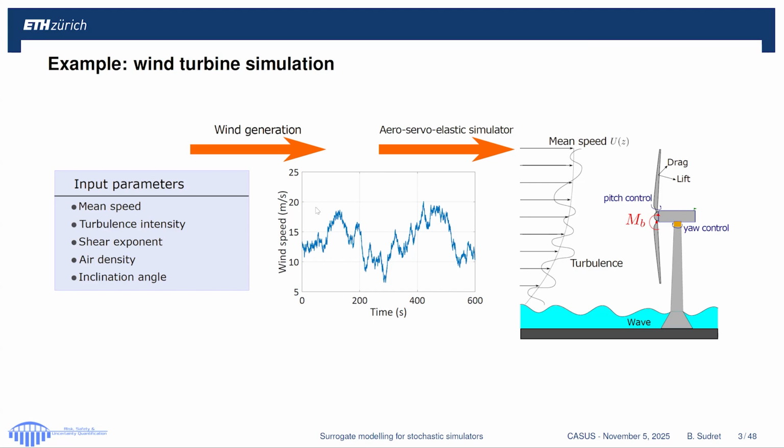So you have Gaussian variables everywhere, and the power spectral density, whatever. So for just the same value here, you get as many wind fields as needed. And then when you map them onto the structure here as forces, and you compute the resulting produced power or resulting forces in the blades, in the tower, and everything, this is different. Okay, so for a given set of parameters, you now get a distribution of, for instance, bending moments of the blades or produced power. So that's the kind of problem we want to address.